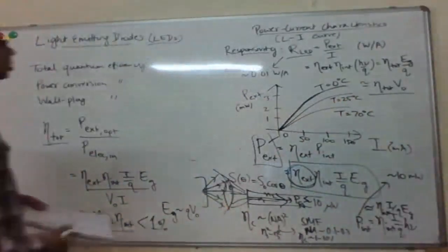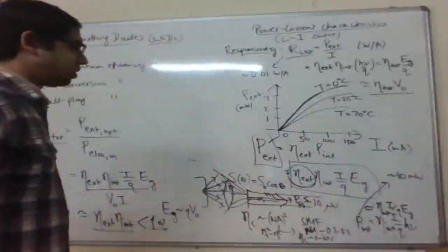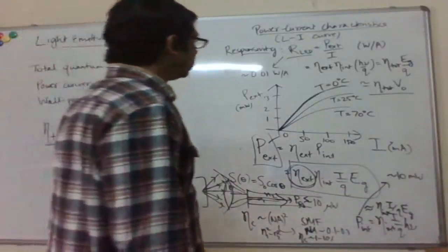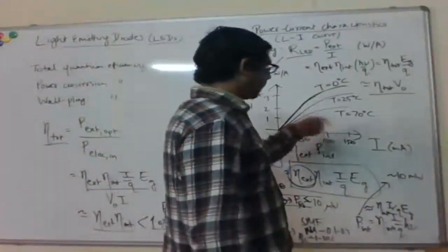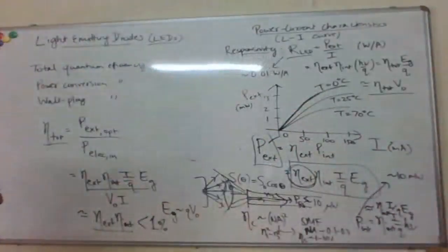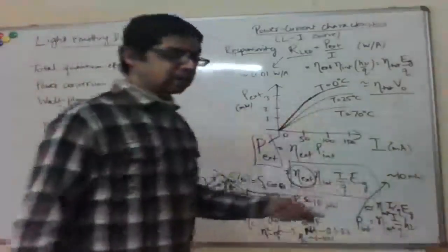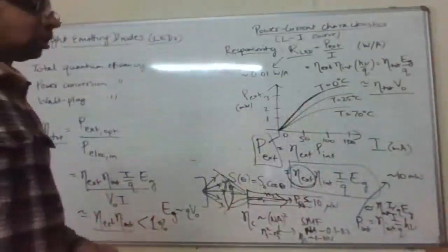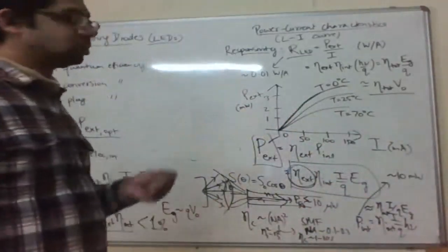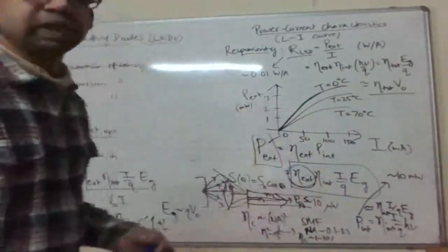So that's another reason why you want as high an internal quantum efficiency and radiative recombination as possible, because any non-radiative recombination also increases your heat dissipation and the internal temperature of the device. With increasing temperature you are increasing the defects and traps within the material, which increases the collisions between charge carriers and the non-radiative recombination.